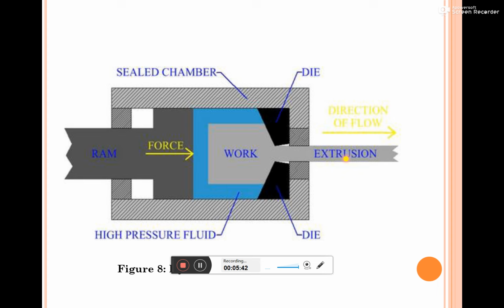This manufacturing process has advantages like no frictional forces, because here the ram does not have any direct contact with the workpiece. We use high pressure fluid by which the force is applied. That's why we can avoid such frictional forces in hydrostatic extrusion. One of the main limitations is that setting the workpiece inside, and the tooling and machining setup, are difficult or complicated in this process.